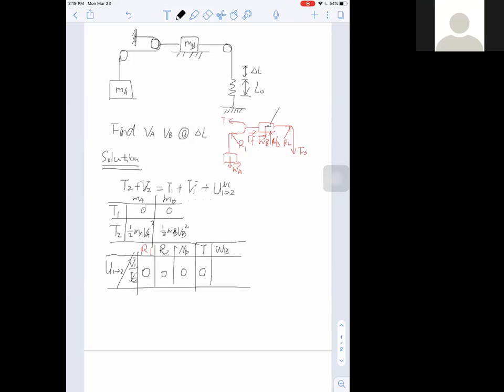Let's call this line potential energy equals 0. So at that height, the potential energy equals 0 for block B. And since block B only moves in the horizontal direction, at position 2 there will be no potential energy. It will be the same height, therefore V equals 0 at both V1 and V2.